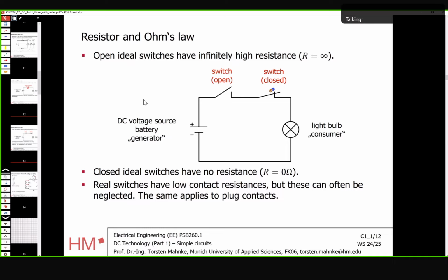Of course, many students use these breadboards for years, so they are not all perfect anymore. Sometimes you see very strange effects when you build your circuits, and then you have to find out what the problem is. Every couple of years, you even have to buy new ones because they don't look good anymore. They look like they've melted.